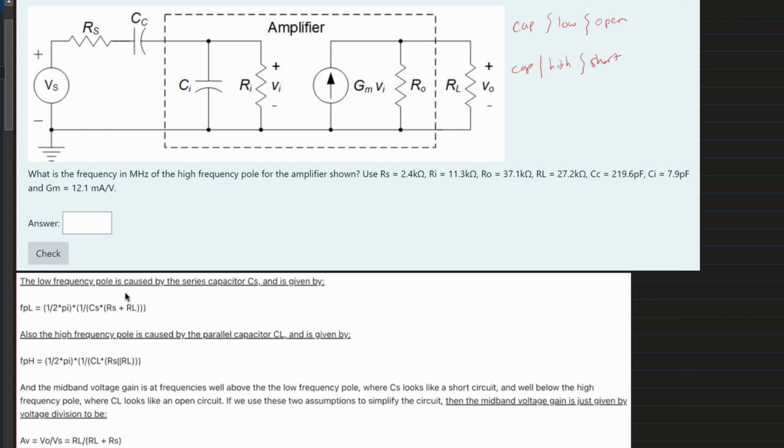The way I remember it is that for low, it's LO, and I tie the O to O for open circuit. So low is open, and then the capacitor at high is just short, because it's the only other thing it could be.